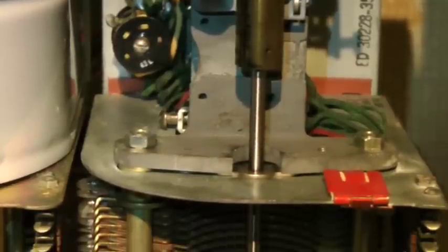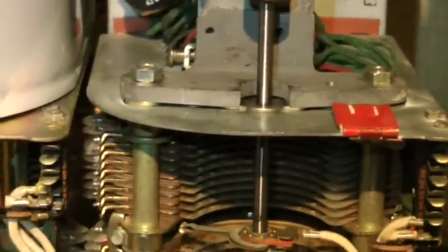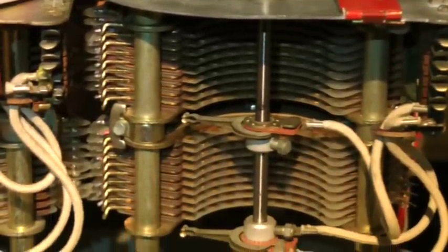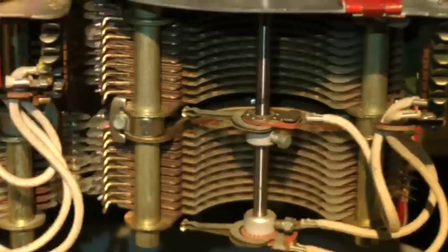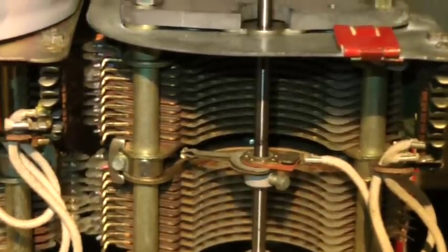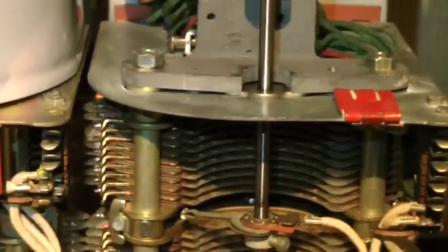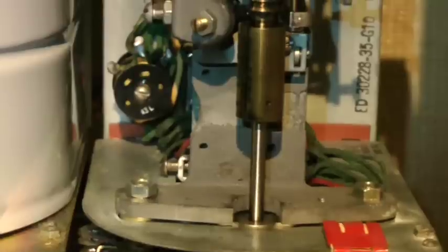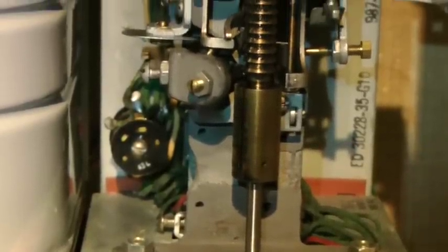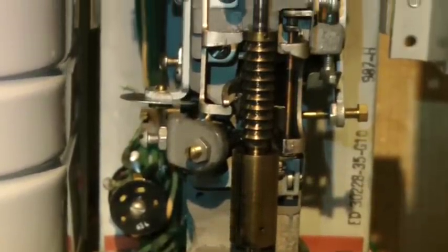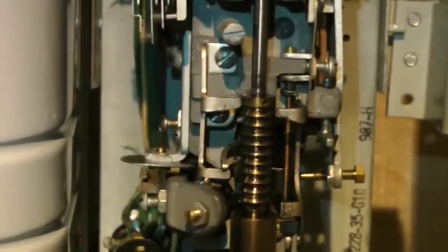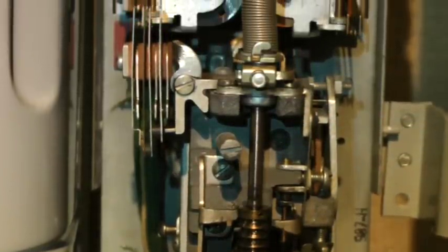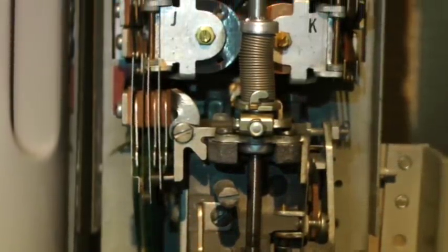The second category is the type of ringing that a connector can provide. Some provide only one ring type, which is a long ring, and that is what this connector provides. Others provide two ring types, a short and a long, and yet others can provide 5 coded combinations of short and long rings to serve up to 10 stations sharing one line. And then there are harmonic ringing connectors that provide different ringing frequencies to telephone sets tuned to respond to a specific frequency.